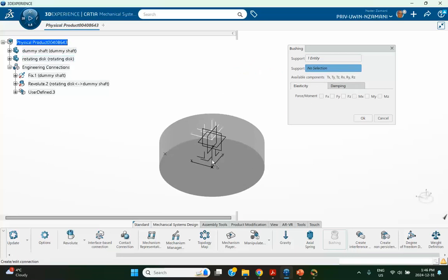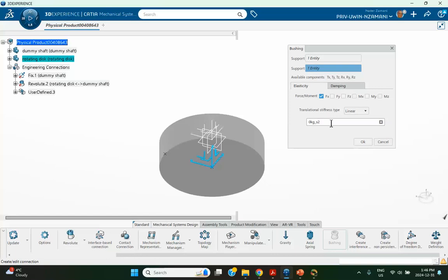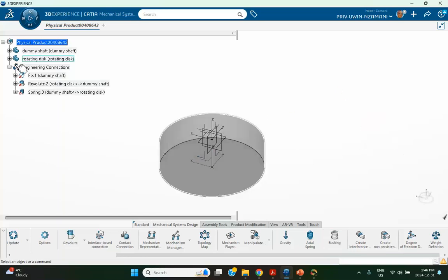Excuse me. The second one is the one for the disc, and you click on the elasticity, click on the f of x, and there's the stiffness, 176 point. I put down 7, but I think it should be 175. But I'll use 7, whatever I told you. That's fine. If there is the damping, then you go and get the tab and put the damping in it.